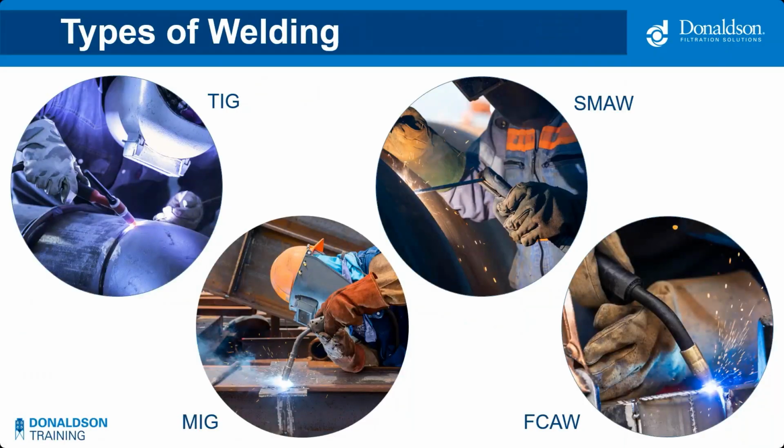There are many welding processes, but the key point is this. Every welding process produces fume. Whether it's TIG, MIG, stick, or flux core, the differences are mainly in how the arc is created and how shielding is provided, not whether fumes exist. Some processes create less visible smoke, others create more, but visibility does not equal safety. From a health and facility design standpoint, the takeaway is simple. If there is an arc, there is fume, and it needs to be controlled at the source.